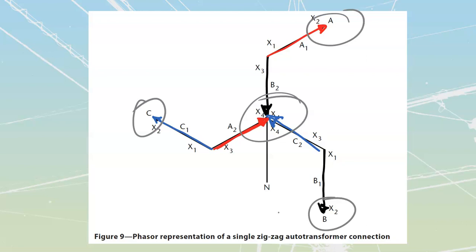What this does is it provides a neutral, where I would not normally otherwise have a neutral. So if I've got a delta connected secondary system, I can create a 3-phase 4-wire system. What you cannot do is just start throwing transformers, Ys and deltas together on the same system without properly looking at them in engineering, because you can result in some serious line-to-line shorts.